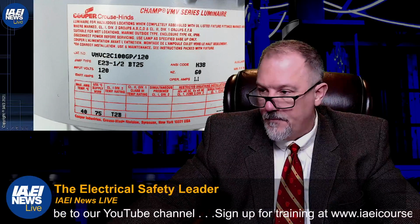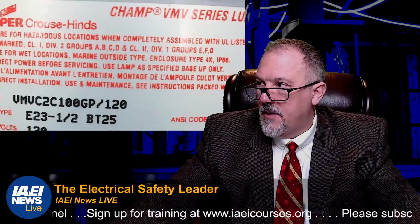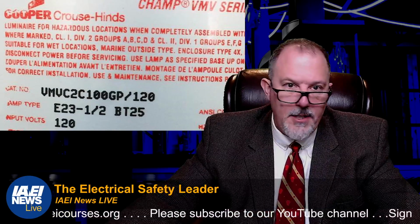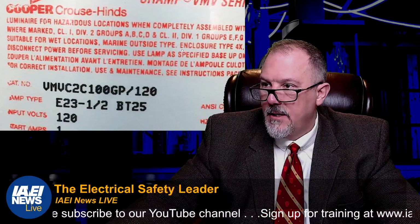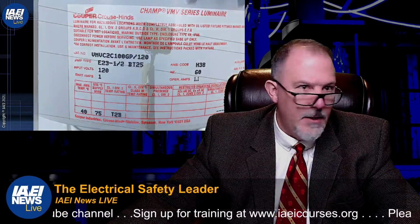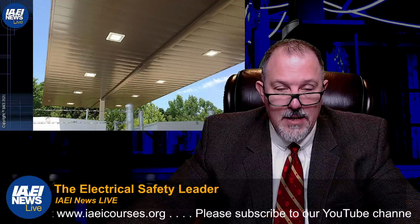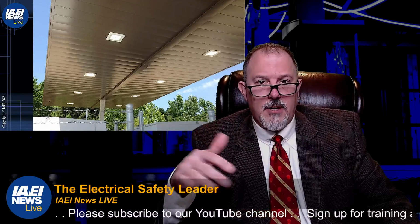Here's another one. Luminaires for hazardous locations when completely assembled with the fixture fittings. Suitable for wet locations, right there. Marine outside type, 4X. Says it right on the fixture itself. There's a wet location. That would not be a damp location. These, I would argue, probably are not wet locations. They're probably damp locations just because they're under the canopy.